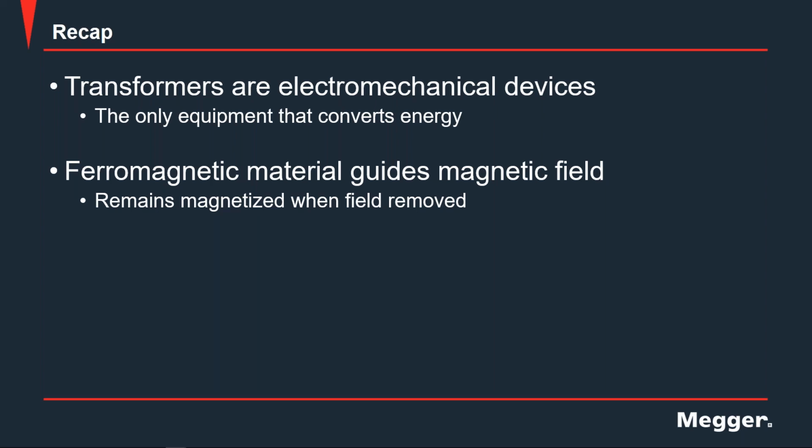Magnetization can occur because the transformer was taken out of service. We don't know where in the cycle it was taken out, so we have to assume that there are some remnants still on that transformer. If you did your winding resistance magnetic test, you will leave the transformer in a magnetized state if you do not do demag afterwards. And then finally, let's say your solar flares or your geomagnetic influence could also magnetize your transformer.